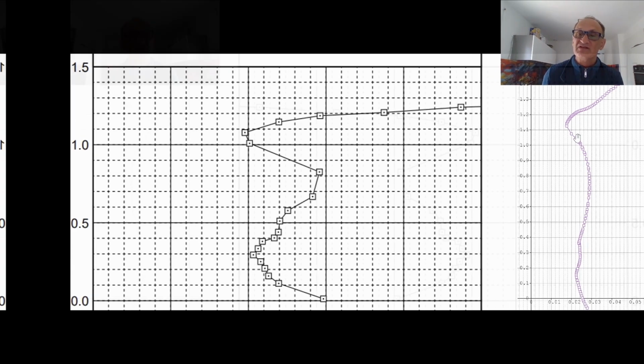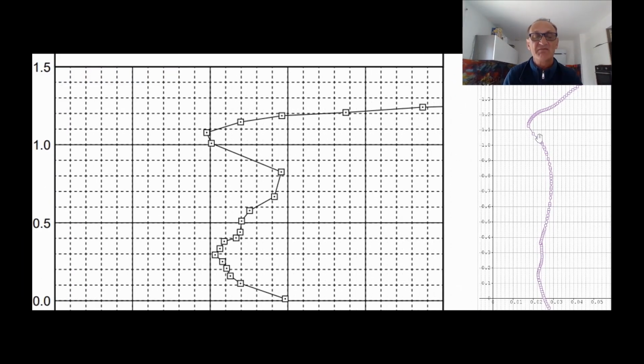So the conclusion is, if you are aiming at the right spot for what the profile is designed for, so this profile is probably designed for 90,000, 100,000 Reynolds, and you are still at a high enough level of Reynolds, in this case Xfoil predictions are very reliable. Except that, of course, we have a top lift on Xfoil that is higher than reality, but this is usual with Xfoil.